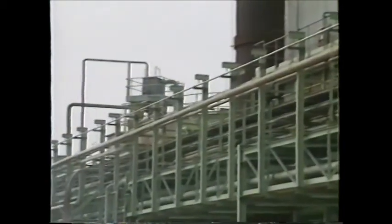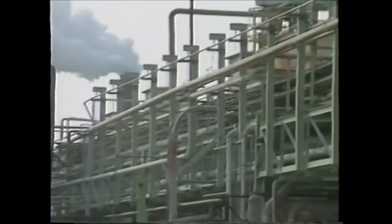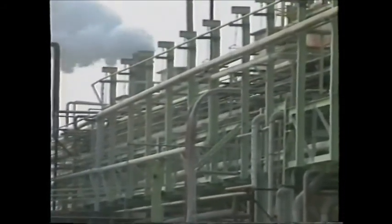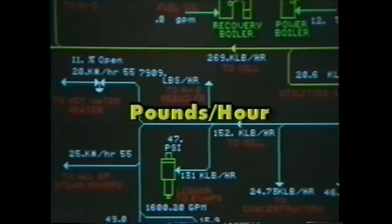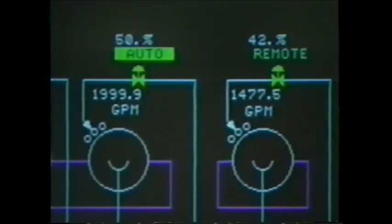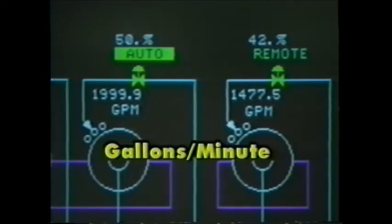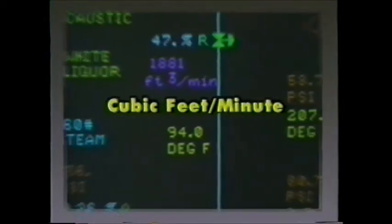Flow rate, or simply flow, is defined as the quantity of a fluid which moves through a pipe or channel in a given unit of time. The flow of steam is usually measured in pounds per hour, or where flow is high, you may see steam flow indicated in hundreds or thousands of pounds per hour. Liquid flow is frequently expressed in units of gallons per minute. Gas or air flows are usually measured in cubic feet per minute.